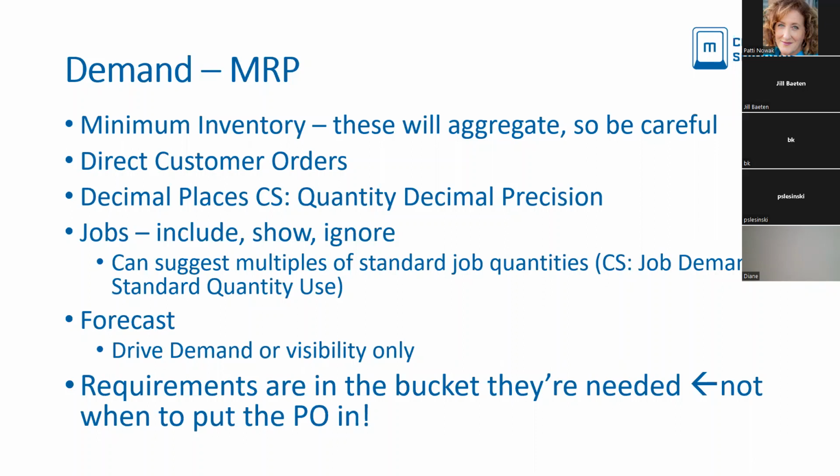But what if you only produce 120 things with that non-standard job quantity? The same 2 hours are spent in setup, and now they're allocated over a much smaller quantity, and each thing gets 1 full minute of setup time, 120 minutes of setup time with 120 output parts. So you get a lot less bang for your setup buck. When you get a nice simple calculation like that, it's pretty easy to see why standard job quantities are important.